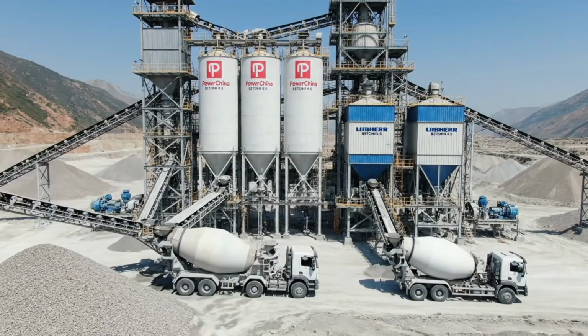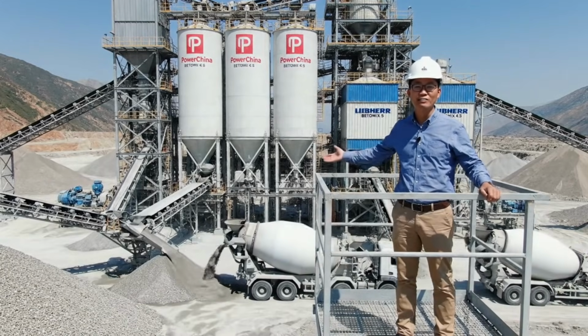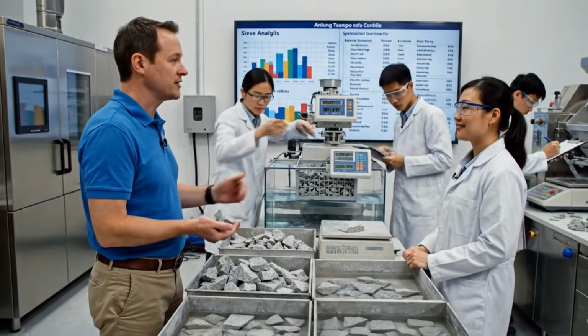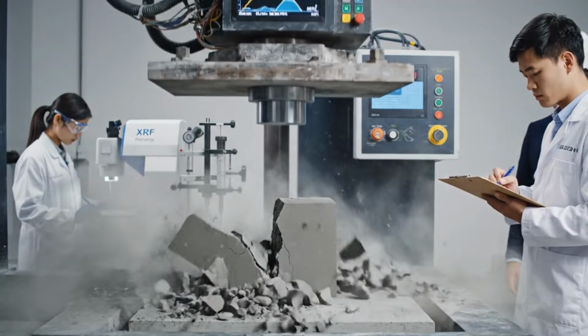This is the heart of the operation, the Liebherr Betomix plants. They will produce over 15 million cubic meters of C100 grade self-healing concrete. They're testing everything, right down to the specific gravity of these 20-millimeter samples. Yep. Look at that failure point. Reaching over 58 megapascals confirms the strength we need for the project.